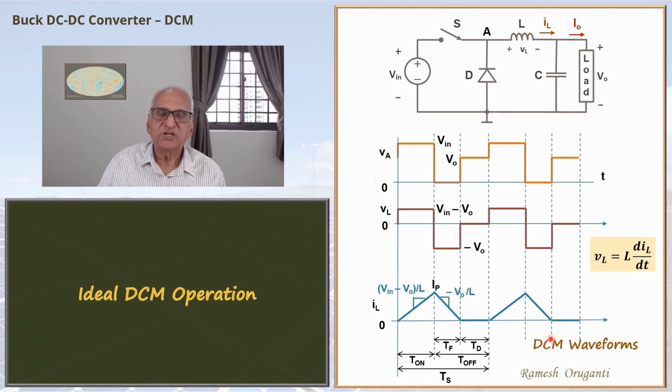The VA voltage has a DC component and a periodic part. The periodic part has the switching fundamental and the harmonics. The business of this LC filter is to get rid of the fundamental and the harmonics and just let the DC part in VA go through.